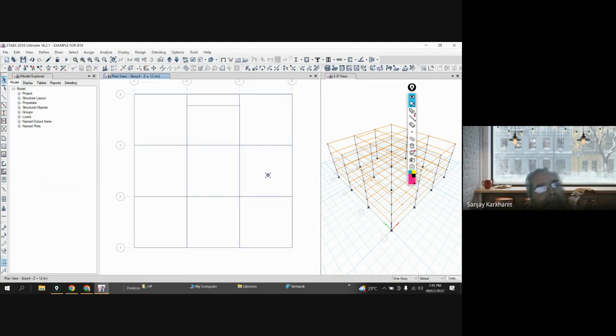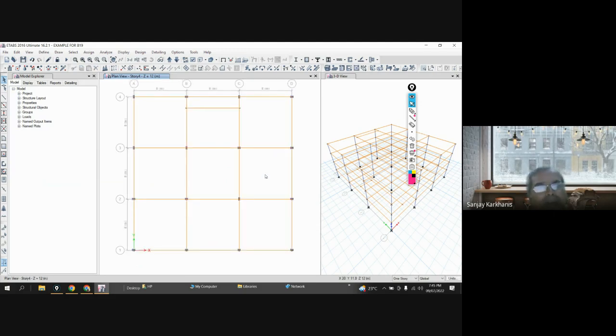Clear? Yes, sir. So with this facility, you can divide the beam, you can join the beam, or you can have a point added on that. But never ever understand, physically you may find the point on the beam, but you have to check whether the point is connected to the beam. If the connection is not there, then there will be a separate point. Okay,